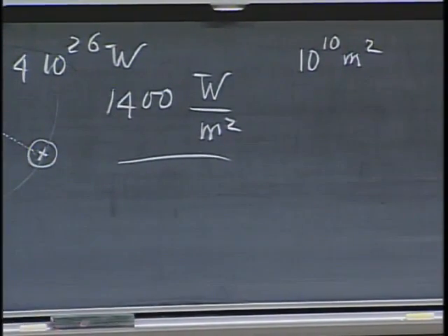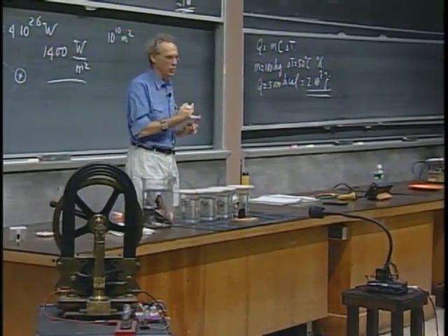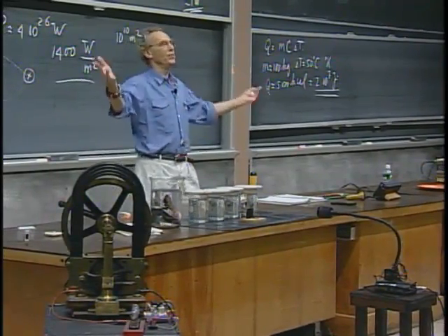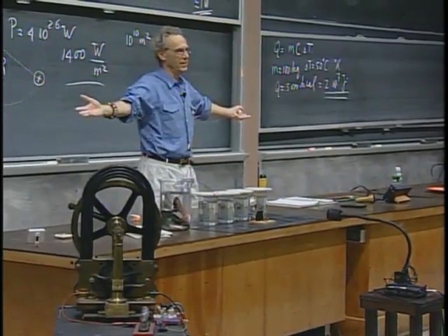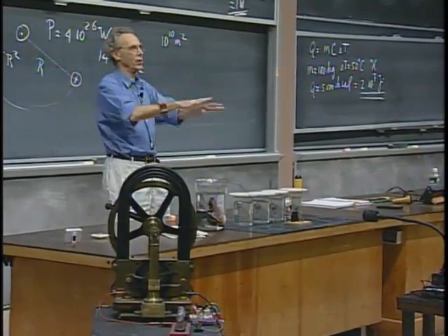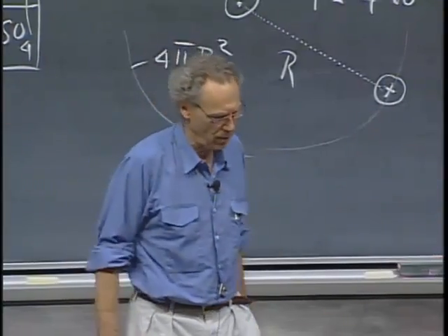However, there is a catch. There is day and night, which we haven't allowed for yet. We just assumed that the sun was always there. There are clouds, and then the sun rises and the sun sets. And of course, if the sun is at the horizon, and here is your plane where you try to absorb the sun, you get nothing. So you have the cosine of the angle has to be taken into account.